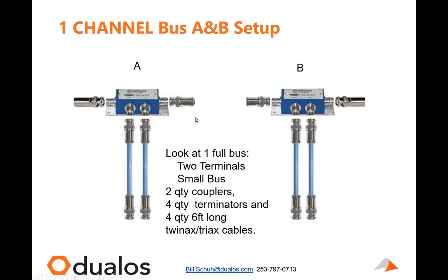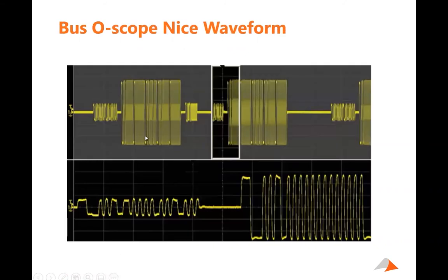Yep. One other thing that may be fun here is looking at what the data bus would look like on a scope. As you look at the signal, this is a really clean signal. You see it's a Manchester waveform, and it has a sync at the beginning, and then ends in an odd parity.